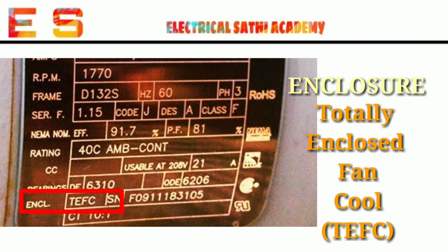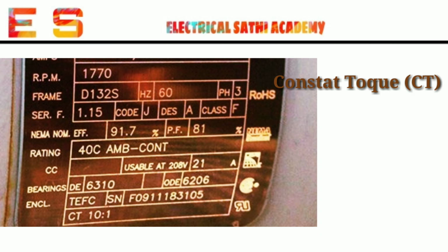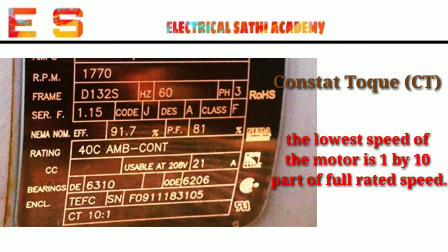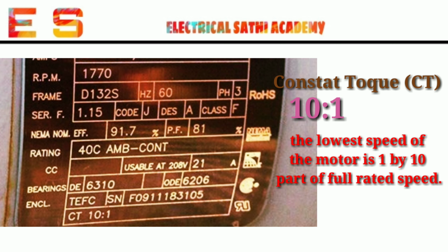TEFC means enclosure. TEFC means totally enclosed fan cooled. CT stands for constant torque, which is 10:1. Here 10:1 ratio means the lowest speed of the motor can only be 1/10 part of the full rated speed.